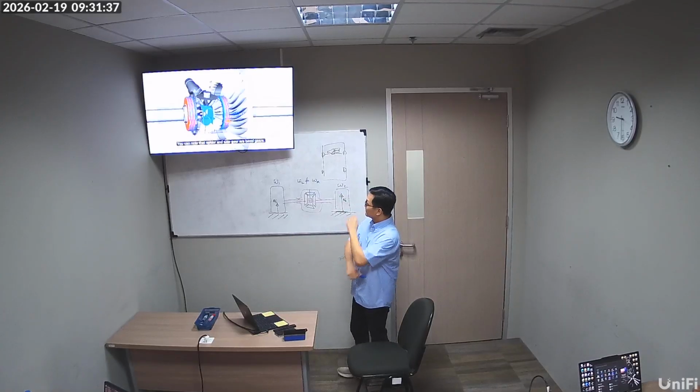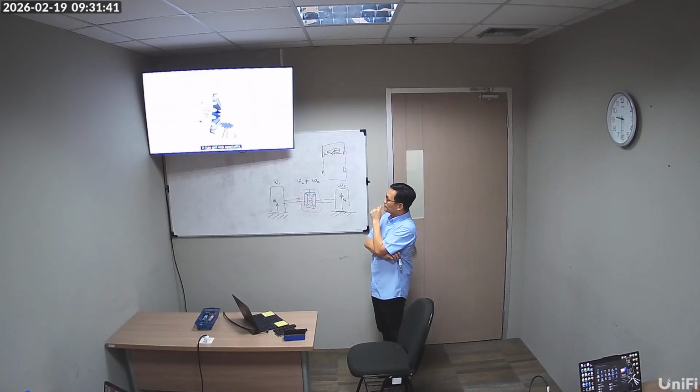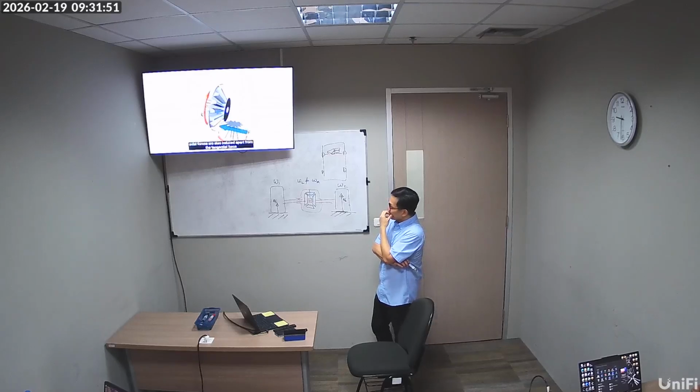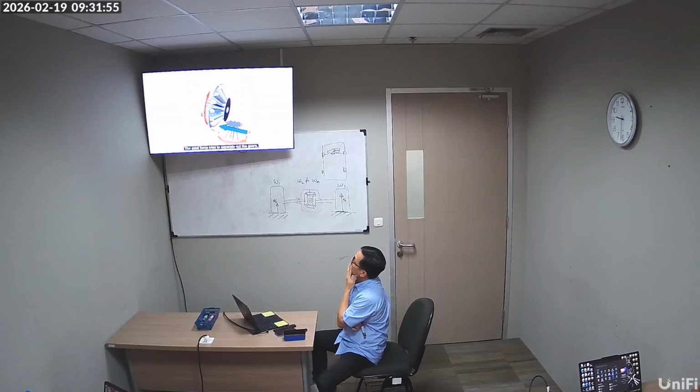You can note that spider and side gear are bevel gears. It has got one specialty. When torque is transmitted through a bevel gear system, axial forces are also induced, apart from the tangential force. The axial force tries to separate out the gears.